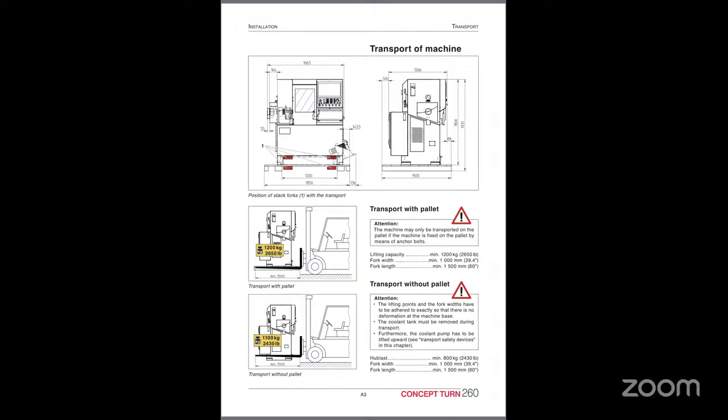So lifting the machine is a very dangerous thing, because the approximate weight of the machine is nearly between 1,100 to 1,400 kilograms. So to lift this machine, we can use a certified forklift or overhead crane. Never use hand lifting, improvised lifting, or one-side lifting. If the center of gravity changes, the machine will tip over. So use the lifting points only to lift the machine.